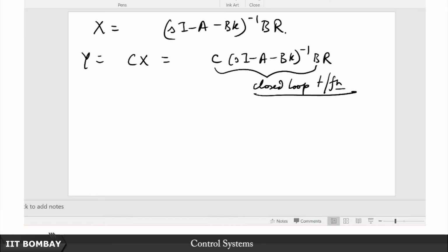From that observer you extract the states, which you always can, because after all this is just a model which is a piece of code for you, and then using those estimated states x hat you design a state feedback, and those states x hat will eventually converge soon enough to your actual state values x, even if your initial estimates are not exact, because your observer poles have been placed suitably on the LHP and suitably farther away from the imaginary axis, so that your observer's error, the error variable, that is x minus x hat, converges to 0 soon enough, right.